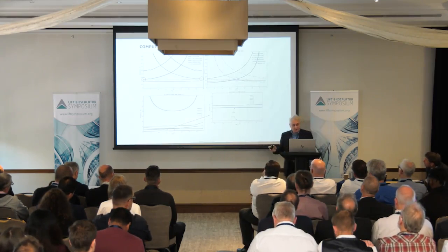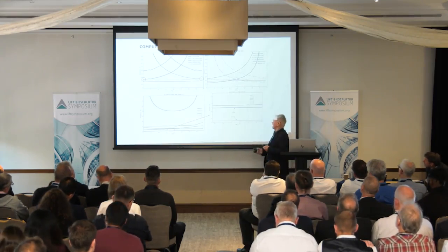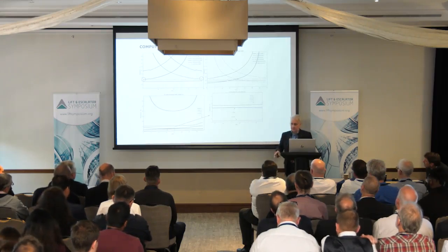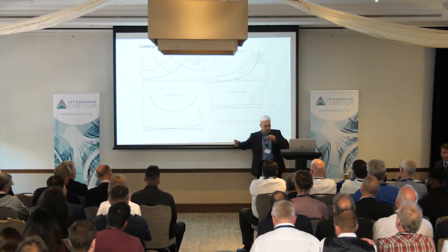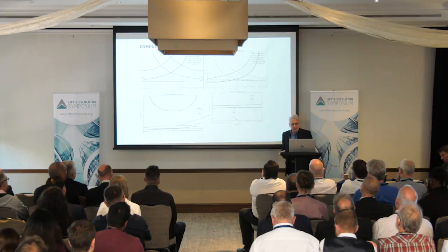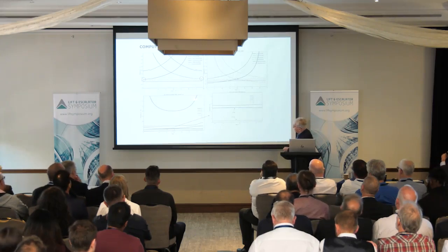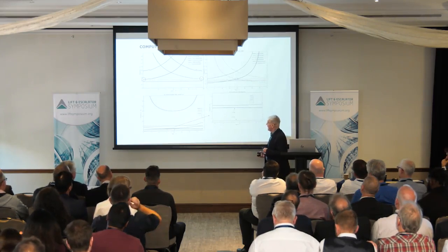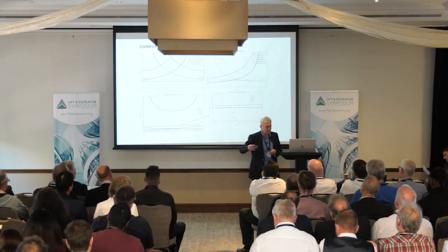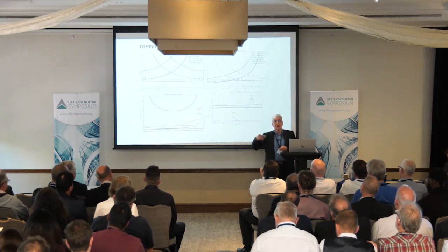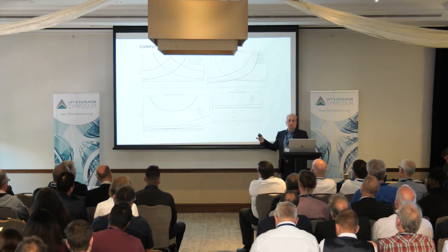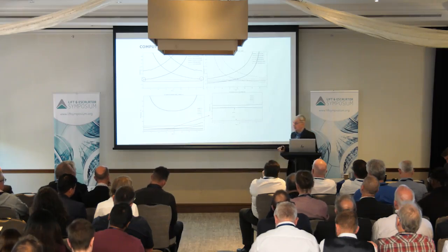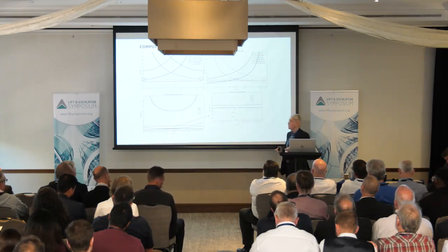There is another set of frequencies we need to take into account to do the calculations. Those are frequencies of the vertical masses. Basically, they move up and down on both sides. However, if you look, there are several frequencies in the vertical direction. They are always above the frequencies of the host building structure. So you would think you don't need to be concerned about them, but actually there is interaction between the lateral motions of the ropes and the motions of the masses.